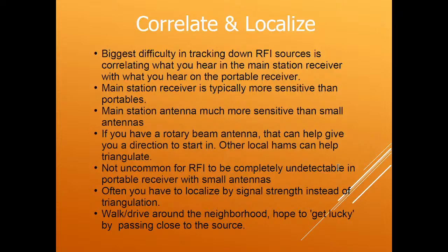But most beams do have some fairly sharp nulls off the back. And if you can figure out where that null is, you can use that as a way of more precisely figuring out the direction that the noise is coming from. And if you have some other hams in town that you're friends with, they can probably do the same thing. And if you're fortunate, they'll be able to pick up the noise source and give you a direction, and you may be able to triangulate between the two of you and kind of hone in on it.